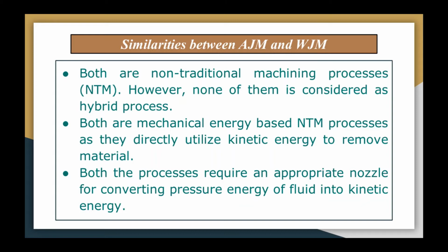Then both processes require an appropriate nozzle for converting the pressure energy of the fluid, that is air in case of AJM and water in case of water jet machining, into kinetic energy in the form of a high velocity jet.